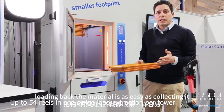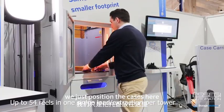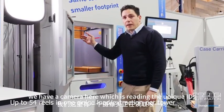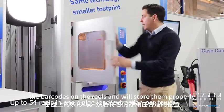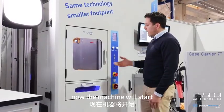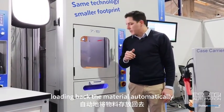Loading back the material is as easy as collecting it. We just position the cases here. We have a camera here which is reading the unique IDs, the barcodes on the reels, and we'll store them properly. I will just close the door and press the button insert. Now the machine will start loading back the material automatically.